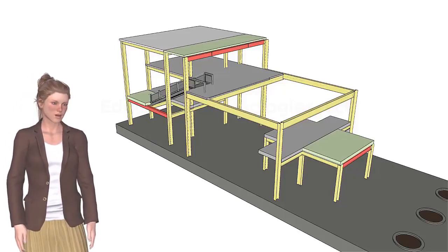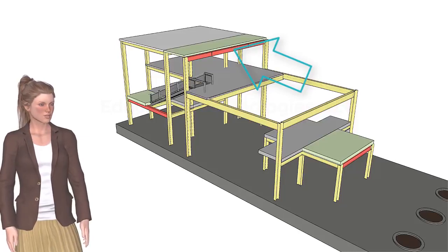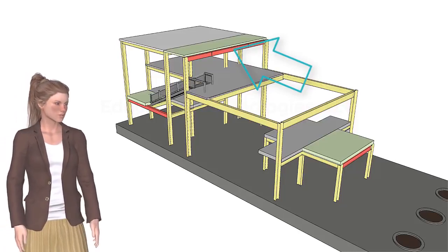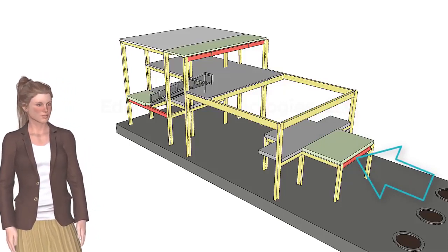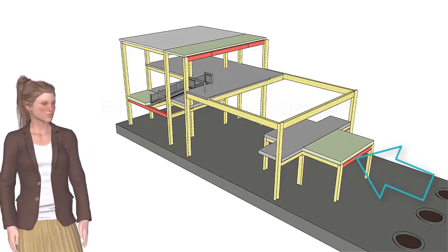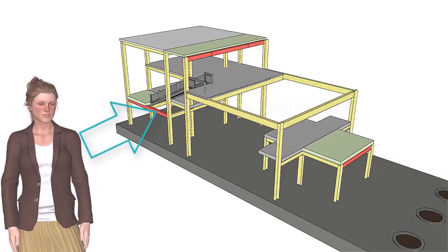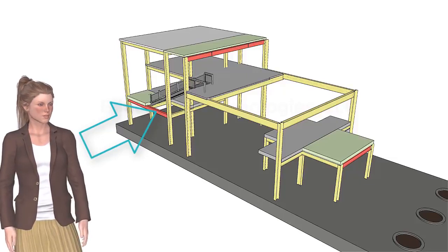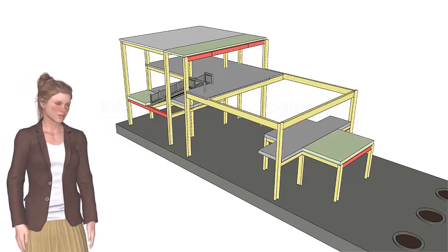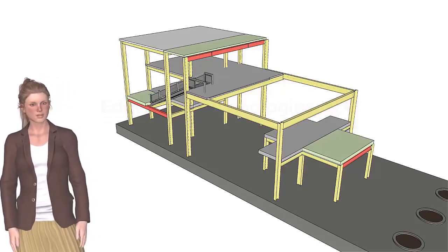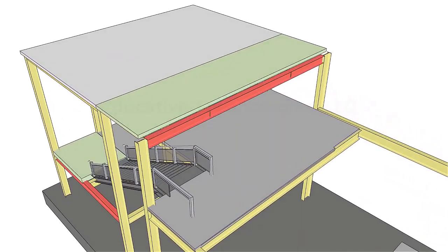We use the beam on the second floor to formulate the shear and moment equations due to concentrated loads only. For the short beam on the first floor, we end up writing the shear and moment equations due to a uniformly distributed load. And the beam on the side of the building covers the case of a partially distributed load combined with a concentrated load. In this presentation, we are going to assume that all 3 beams are simply supported. Let's start with the long beam on the second floor.